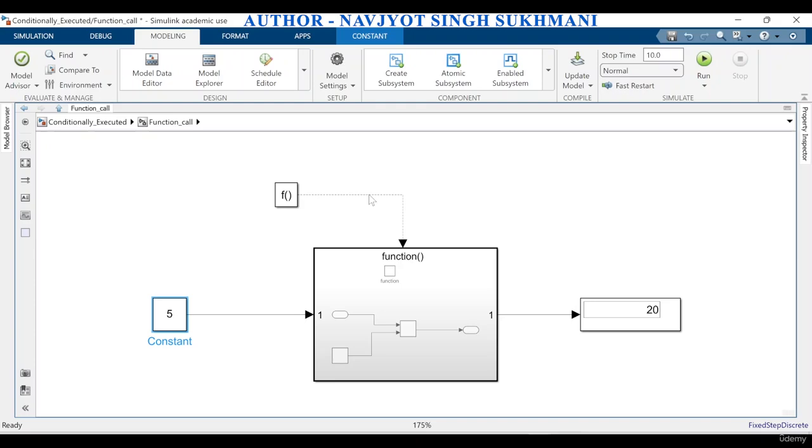So I want it to run at 100 milliseconds instead of 20 milliseconds. If I am implementing the airbag logic inside the collision imminent braking, where that CIB is calling the airbag logic, that airbag opening logic will work on its own sample time, which is quicker than the 20 millisecond time.